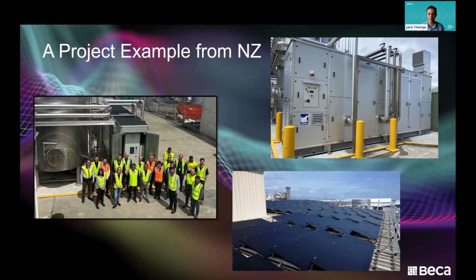Here's a little picture of some of the solar thermal panels we installed, evacuated tube, evaporator panel type arrangement. And you can see there's the heat pump, and right next to it's the big thermal storage tank we put in. At the moment, the system's up and running. We've gotten rid of about 80+% of the existing or the previous gas utilization at the site, and we've improved a bunch of operability and reliability issues that the operations team have been working with.